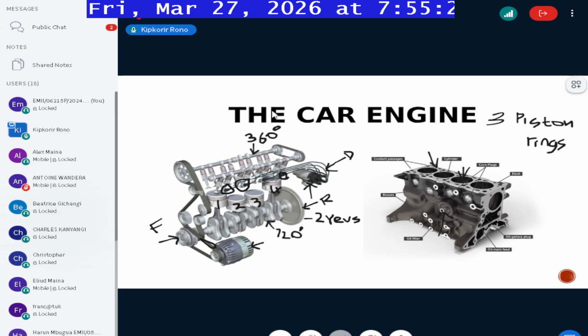So if there's any loss of oil, or you do not have sufficient oil in your engine, then you have what you call oil starvation. Oil starvation can increase frictional losses. Friction energy is normally converted into heat energy. It can cause a rise in the temperature of the engine, and it can also cause damage to some of the parts. So it's not a very good thing. Oil level check is a very critical part of engine maintenance. That's what technicians will always tell you.